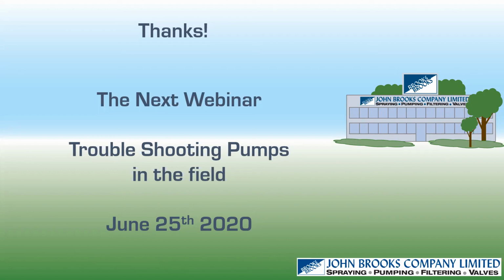What is the maximum percentage of overspeed allowed? I guess that's an Adrian question, but I've always said 90 hertz. Is that a good answer, Adrian, or do you have something different? It does depend on whether we're talking about a 2-pole or a 4-pole or a 6-pole motor. With 2-pole motors, you can go up to 90 hertz probably. I wouldn't want to go much higher than that. If you're going with a 4-pole motor, you can go much higher, even up to 120 hertz.